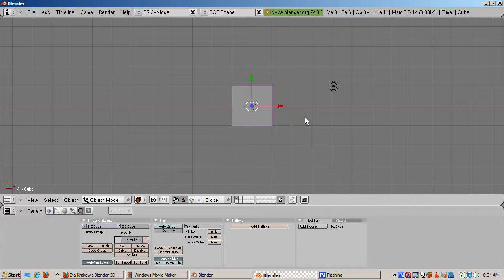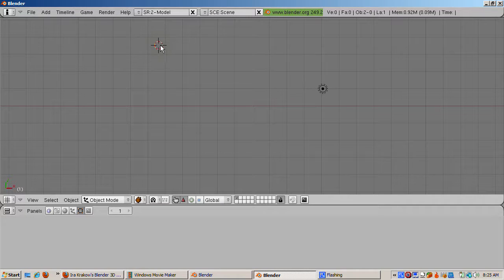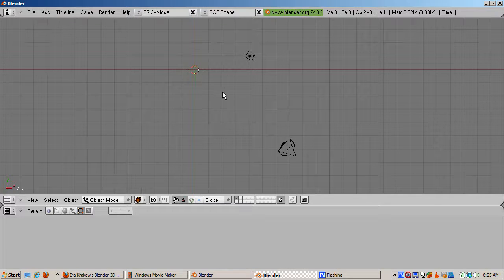So fire up Blender, delete the default cube, right-click, X to delete, and enter to confirm. If you click inside the 3D window, the 3D cursor goes to the place where you click. That's the place where the next object will be created. We want the text to be placed at the origin. X equals 0, Y equals 0, and Z equals 0. To do that, there's a simple shortcut to place the 3D cursor there. Press Shift-C. To create a new text object, you do space, add text.